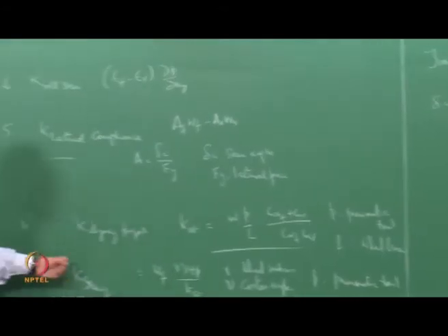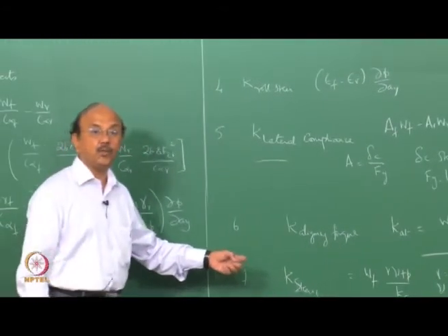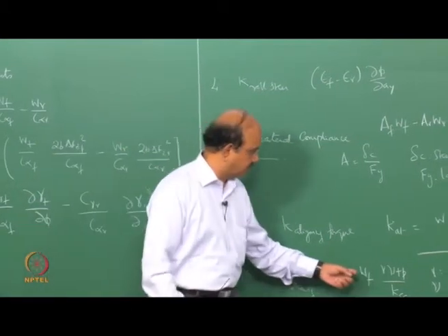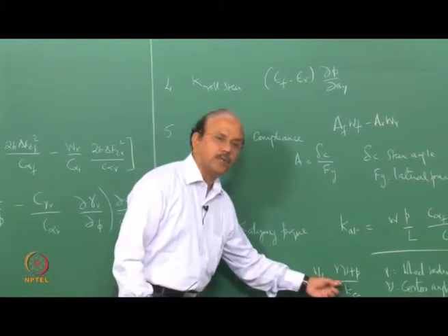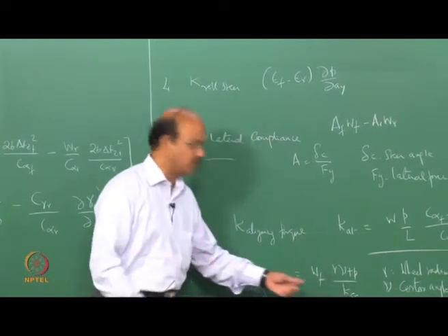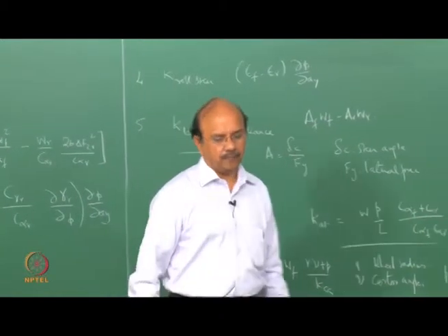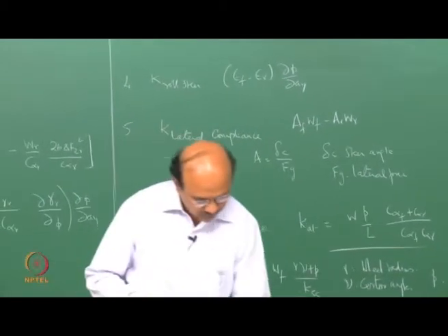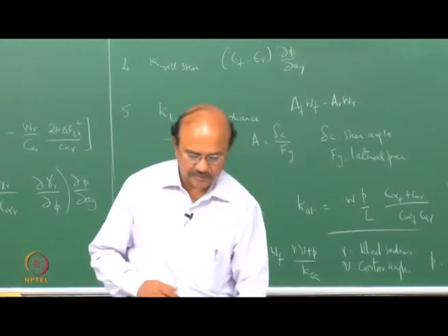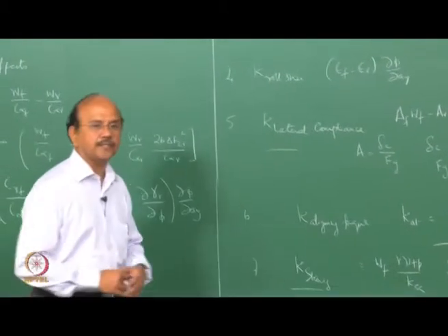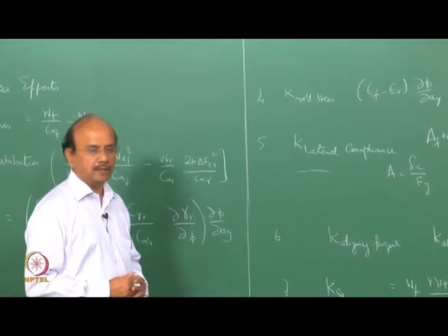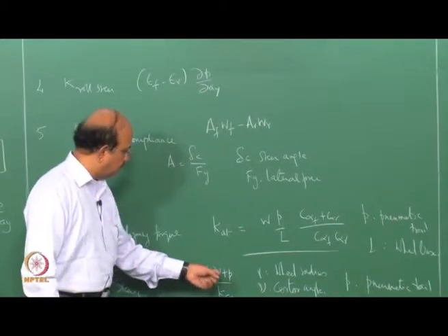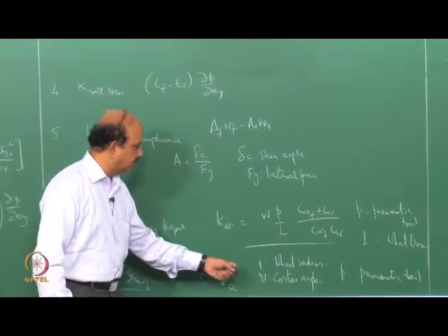So the understeer gradient due to steering has an important component, which, of course WF is known, we call KSS. Here we look at the stiffness or the compliance of the steering, as well as the wheel radius, the caster angle and the pneumatic trail.